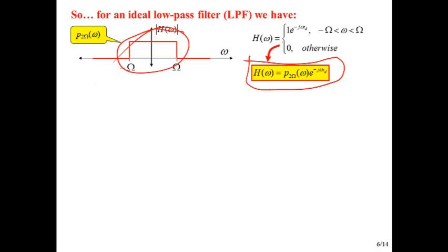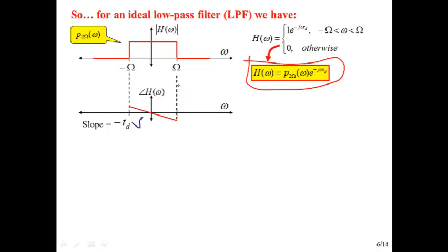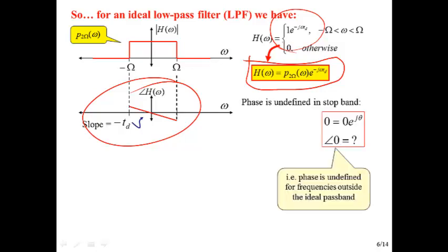Okay, good. So what can we do with that? Well, not yet. I'm getting ahead of myself here. Here I'm showing the fact that the angle that we're specifying here is this straight line. Okay, so we say that an ideal low-pass filter, for that case, any type of filter, an ideal filter is going to have a linear phase in its passband. And so this is just illustrating what it looks like for the low pass case.